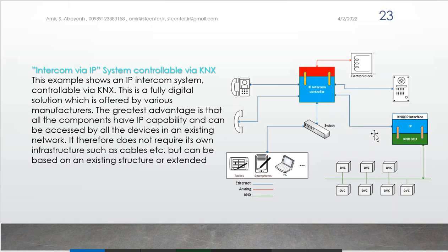And then with the KNX IP interface integrated in your mini server or server of the KNX, you can communicate with the systems. You can see here the lock, you can open it with the wire because we have some analog output. Of course, nowadays we have relay actuators based on IP, so it is possible to connect the lock on the IP side also.